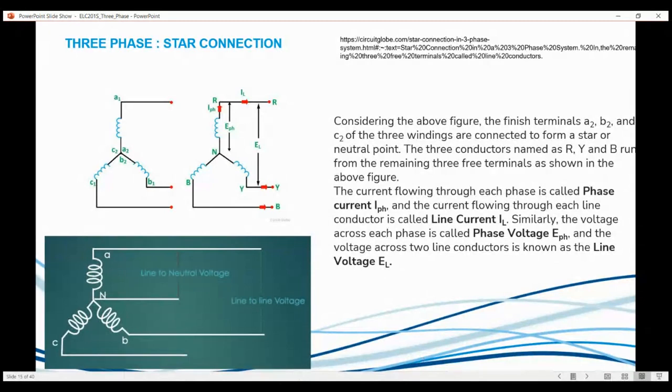Oh, someone's got something. My experience with star delta is we normally use it on motors, and the main reason we use star and delta is so we can reduce the amount of current that is drawn when the motor starts. So instead of using an auto transformer, for example, we use the star. Yeah, we've just lost it there, but yes, that's one of the applications: star and delta starting for motors.